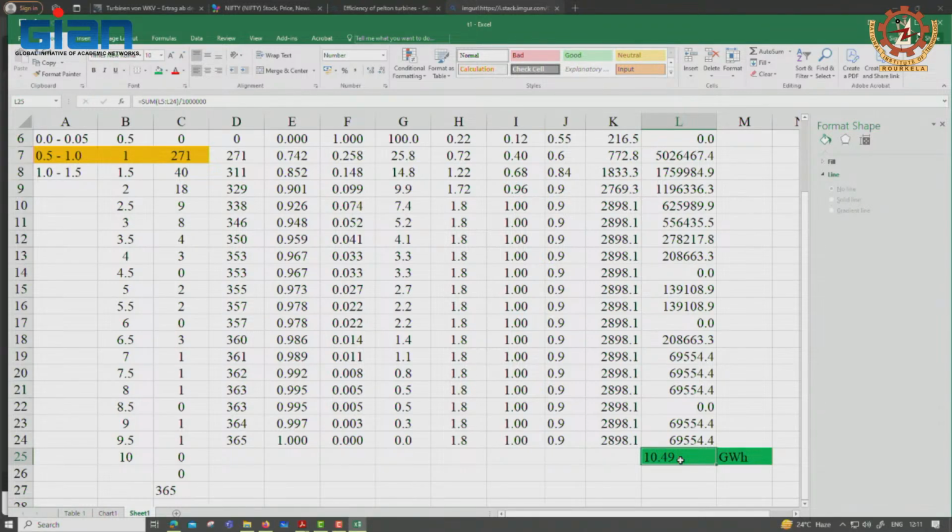So you must do one cash flow evaluation with the Pelton turbine and another with the Francis turbine, and maybe Turgo was also possible, so another cash flow analysis for Turgo. You must get offers for all three from the manufacturer, and then with certain assumptions you can get the civil costs approximately, then the total project cost, then do the economic calculation. But your annual energy generation for the three types will be different.